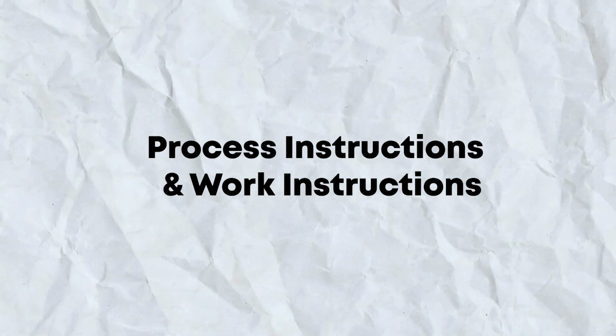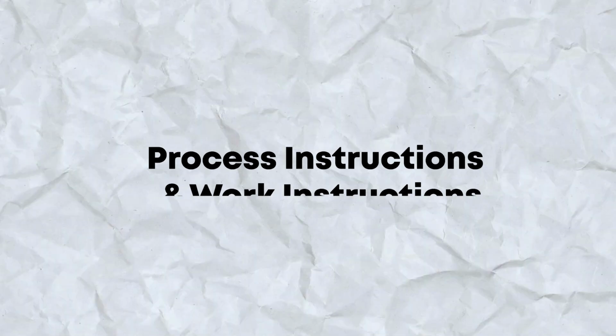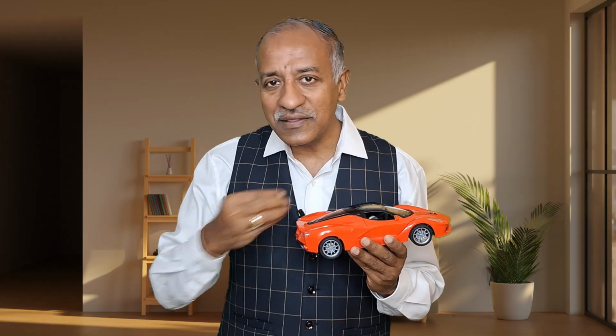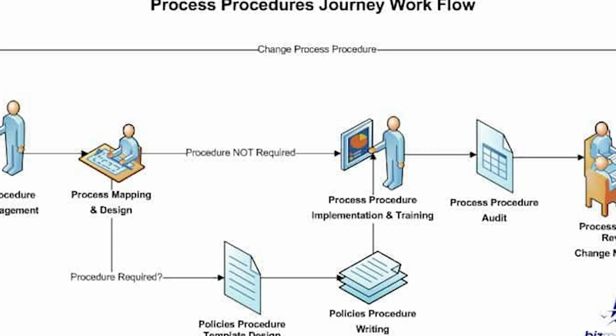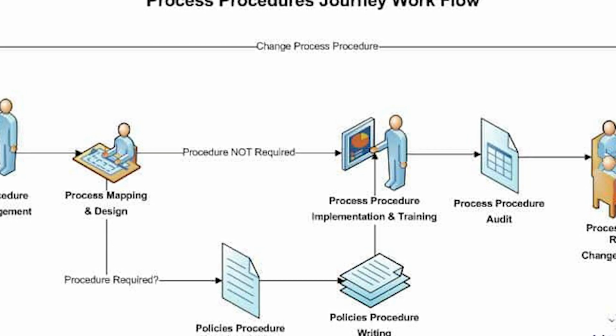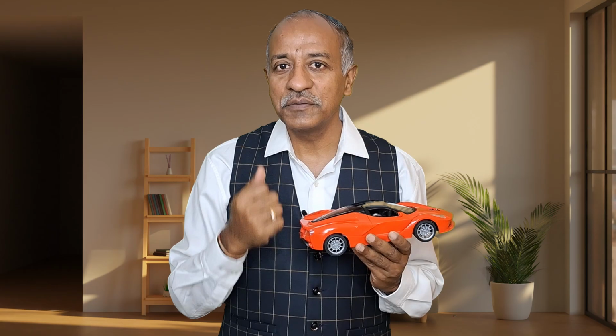Then brings the next point, point number 7, which is talking with respect to the process work instructions. In general, control plans are not being used directly on the shop floor. There is a work instruction which is an output from the control plan which is being displayed. It is talking about all the controls with respect to competency of the people, the special characteristics, the inspection frequency, the sample size, and so many things. So whether the work instruction is incorporating all the things which are coming out from design FMEA, process flow chart, as well as the control plan, that is something important.